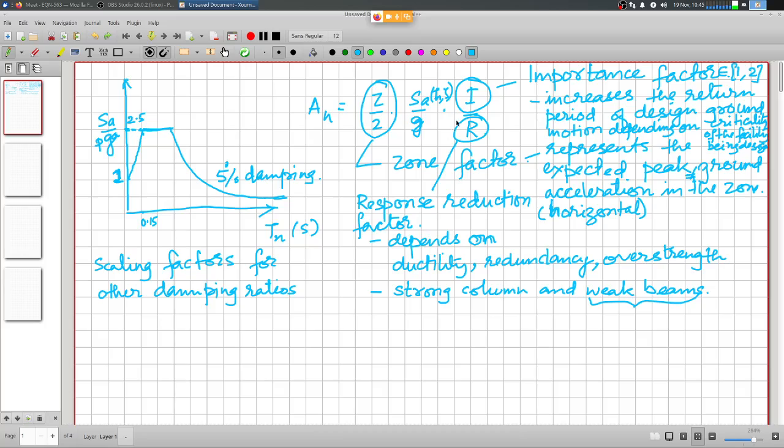So this has to be taken care of during site construction. At the construction site, every batch of steel has to be tested to failure and confirmed that the yield strength is not excessively high,